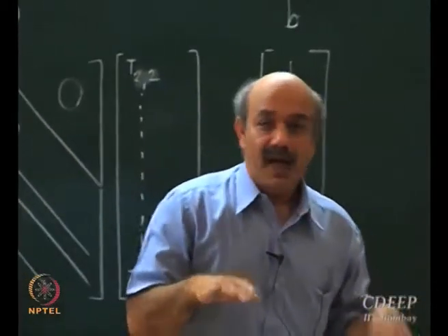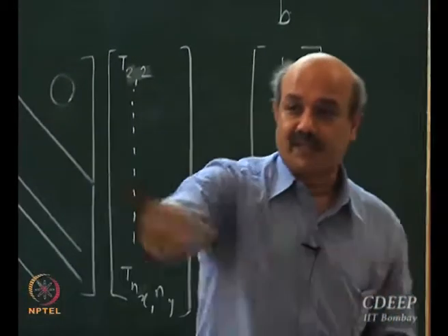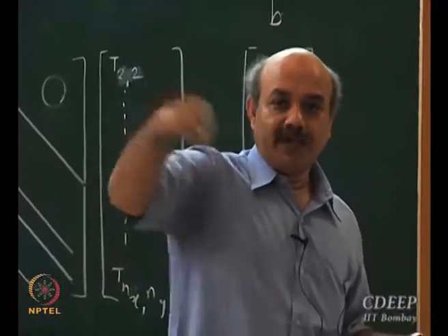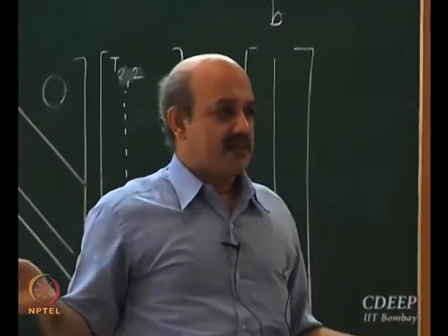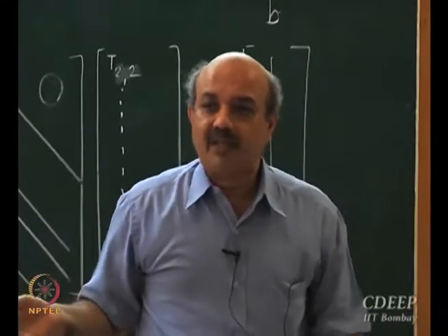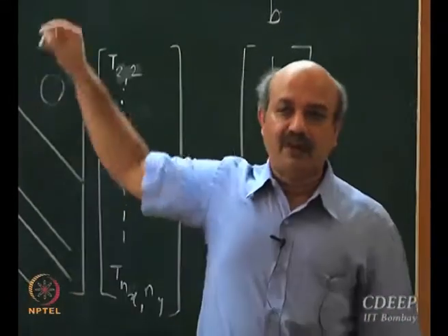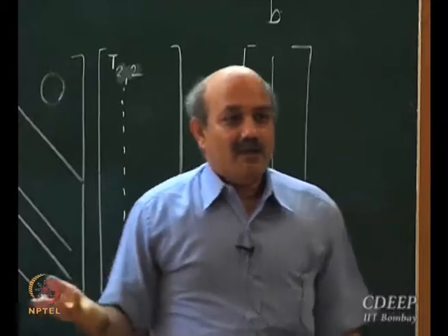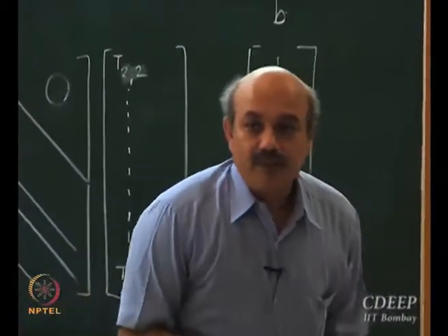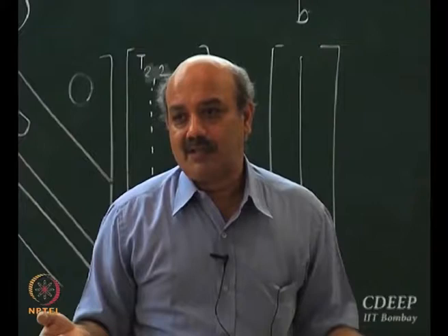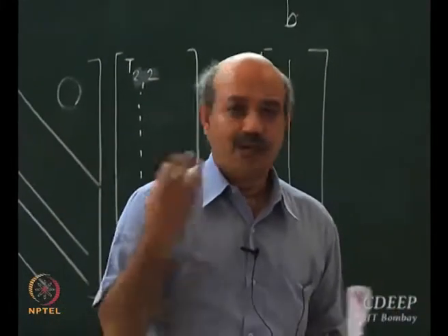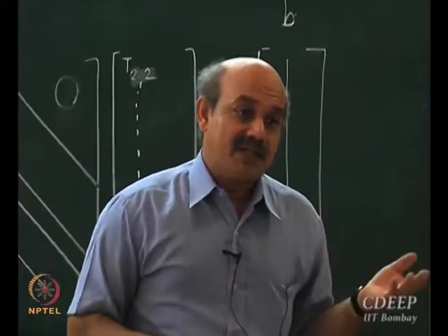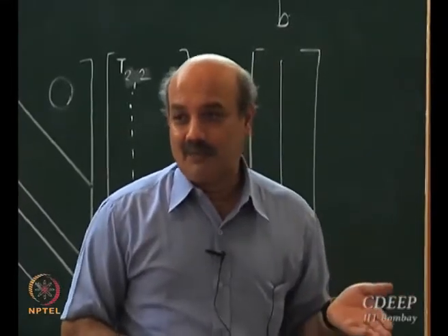So the solution here, actually the true solution, is a surface with one temperature value attached to each point, each xy in this. We are not able to solve this equation at every point, we are able to solve it only at a finite number of points. You will get a good solution if you create more grid points. The solution will improve with more and more grid points, but the computations increase with more and more grid points.